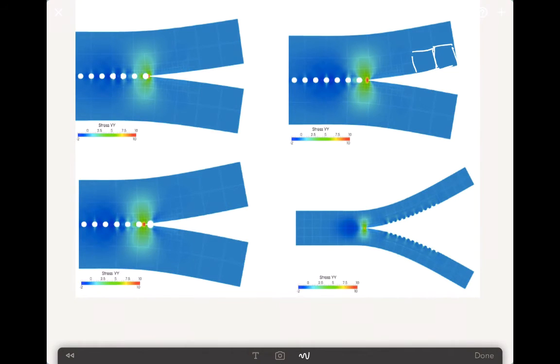Now these look like bilinear elements, but actually they were higher order elements which had nodes also along the edge. Therefore, you can see that you can have a crack which can propagate to the node which is present midway through the element along the length. Now, in order to make sure that we have a good result, or that we are making use of the right number of nodes, we are also going through adaptive refinement.